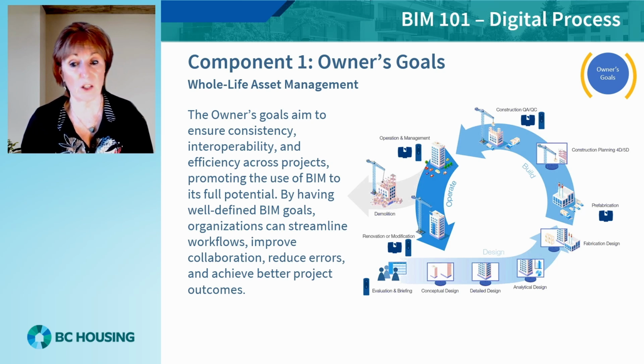For example, space to be retained for maintenance and replacement. Design and construction teams would have to undertake virtual coordination to confirm this goal is met. Asset hierarchy. Parent-child relationships must be provided, requiring a specific data field or naming convention to be created and populated by the design consultants. Digital handover. All specified installed asset data, i.e. serial numbers, etc., and PDF documents, O&M manuals, must be provided and linked to design intent assets.